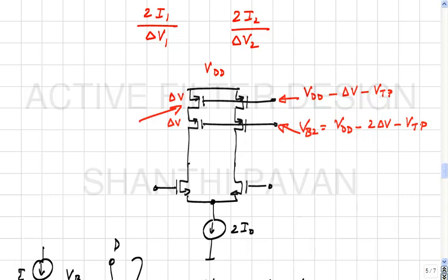Very good. Okay. Of course, like all engineering situations, it's not good to operate on the edge. You will always have some margin. Now, if you do this and add common mode feedback, then you have a transconductor where the DC gain is GMN times RON, because the output impedance of the top PMOS current sources, which was originally ROP, has now become GM ROP times ROP, which is an order of magnitude larger than before. So one can conclude safely that the DC gain is being limited by the output impedance of the NMOS transistors. So the DC gain will approximately be GMN times RO.